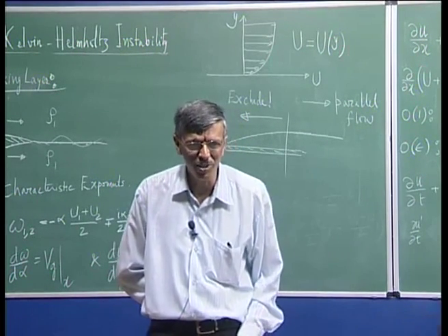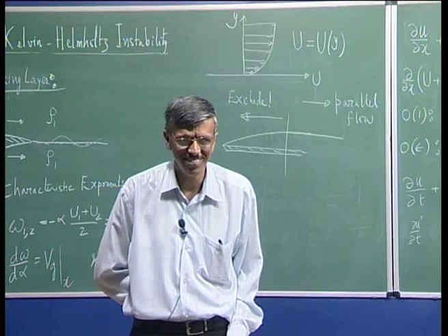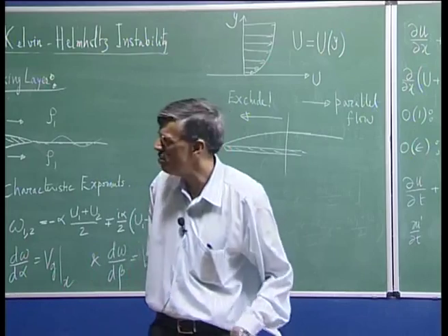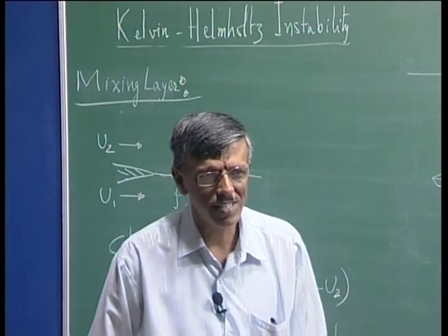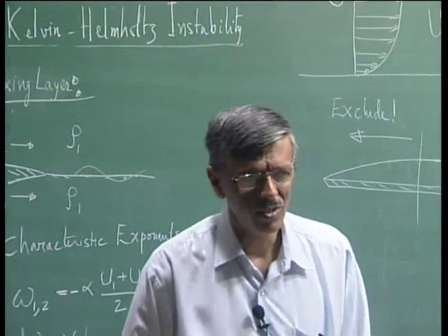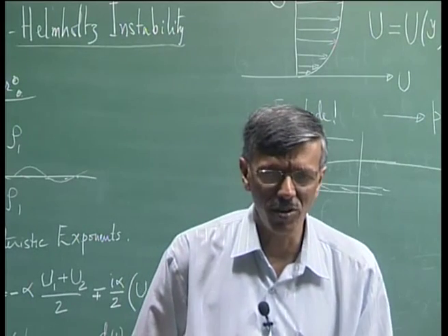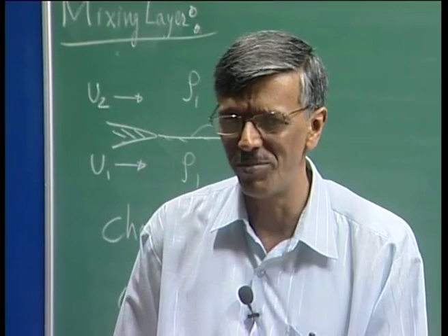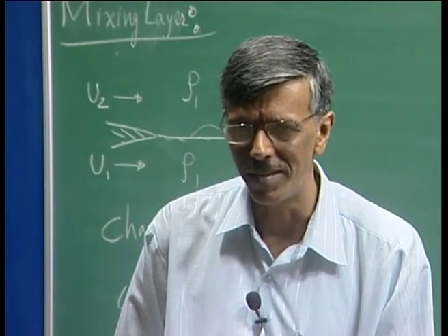When we talk about time, we must have some origin, right. So, if I perform a time integral, we are talking about that receptivity framework, right. If I start a wind tunnel or a water tunnel, then of course at the time of starting, I am not only starting the mean flow, I am also starting some kind of a disturbance field.